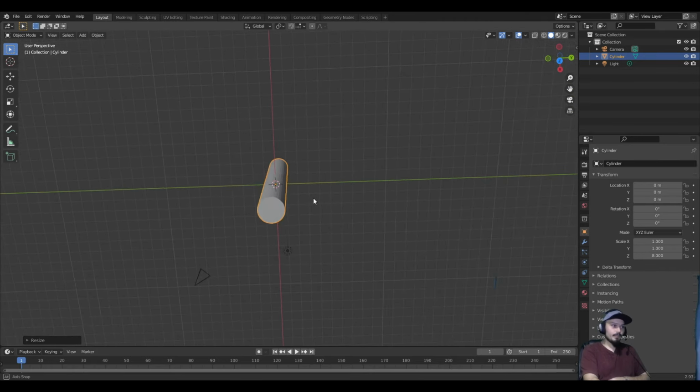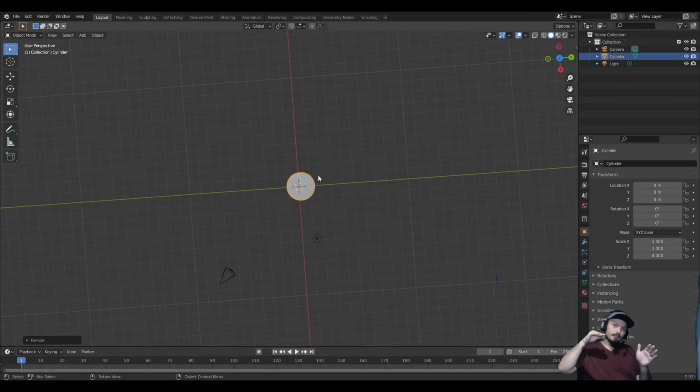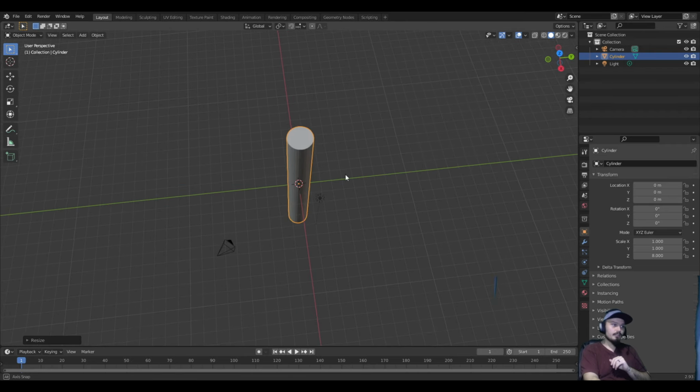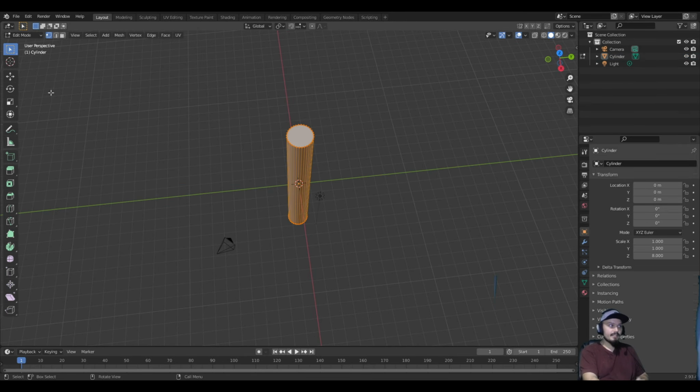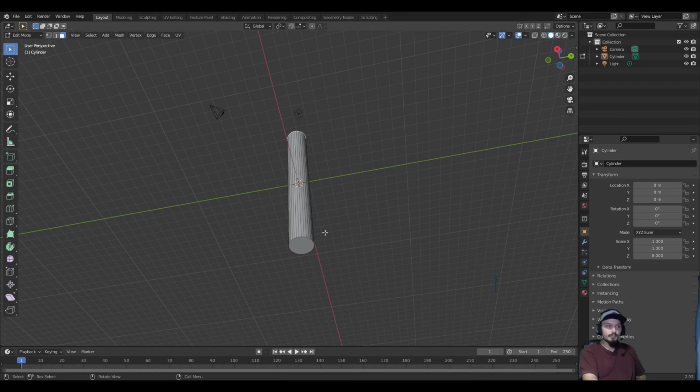The next thing we want to do is we want to actually open this pillar up as our camera, let me move this over here, as our camera is going to be going straight down the center of this pillar. So what we want to do is we want to hit tab, and tab is going to take us into edit mode. If you see this window on the top left, we have object and edit mode. So pressing tab will cycle between object and edit. So when you're in edit mode, you're going to click this third icon here that says face select. Okay, and this is going to choose our upper and lower face. So once you click that, go ahead and click the top face, hold your middle mouse button to scroll to the bottom, and while holding the shift key, because we want to select both of these, you're going to click the bottom face.